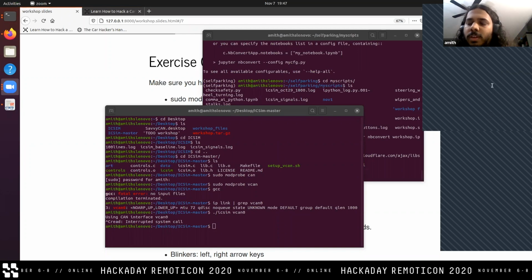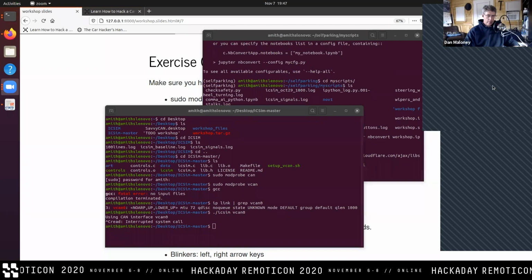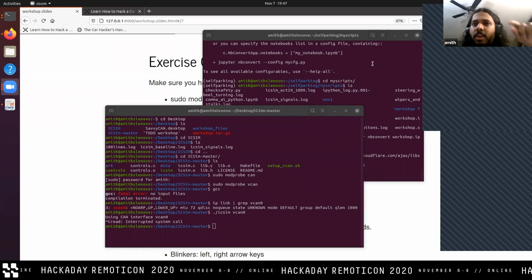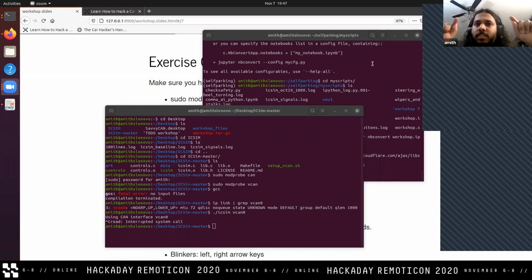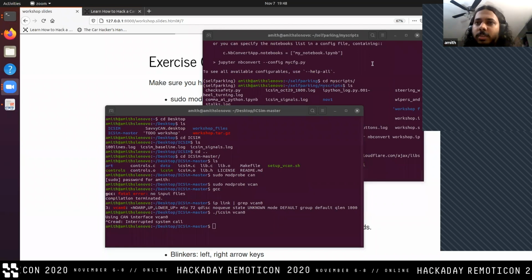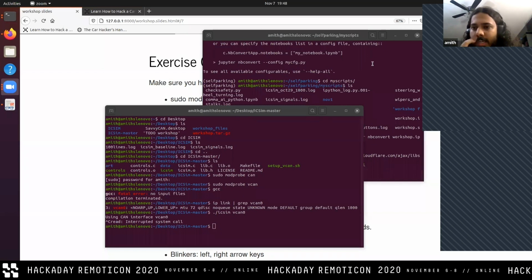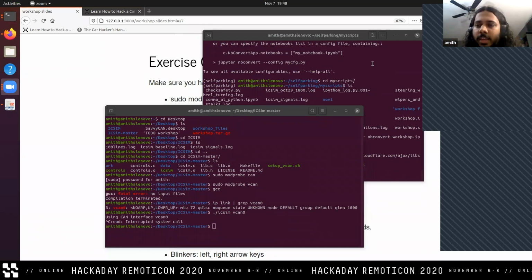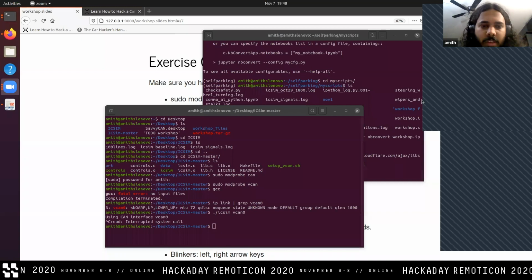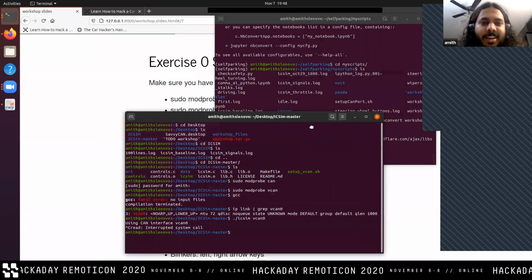Oh, no. So there can be multiple CANs. They can, I think, in automotives, because if you remember the OBD port I showed, the undefined pins are up to the manufacturer's discretion. So they can add multiple CAN networks or add their own proprietary network. Like there's a slow CAN, which is like GM CAN or GM LAN, I forget what the word is. So that's a lot slower. No idea, honestly.